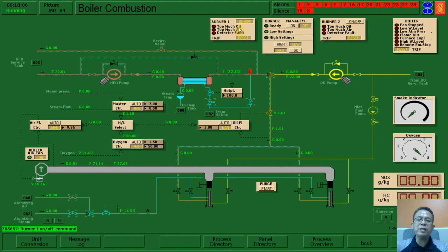By pressing the burner on and off, we find the pilot valve and switch it on, and we can find the fire here from the igniter, waiting for the main fuel. Now it started the main fuel, and we have here the main fire coming from the fuel pump. We are going to wait for the switching off of the igniter. So the igniter is off, and what remains is the main fire.